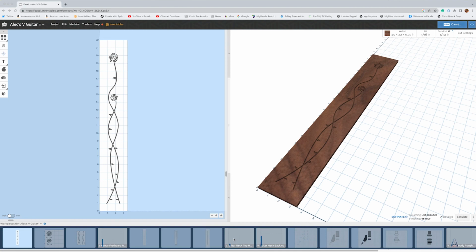Now this is an order that I have been following for many years. And it goes all the way back 20 some years when I first started building guitars by hand using my router and my bandsaw and drill press and all that. I found that by making the neck first, I could then use the neck to establish the shape and size of the pocket for the neck in the body. So I would always make the neck first.